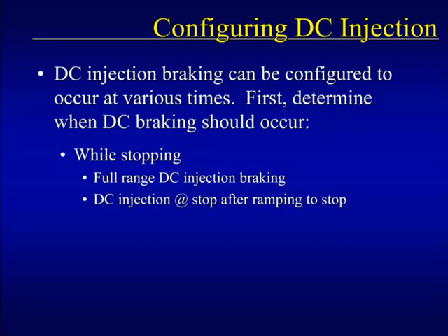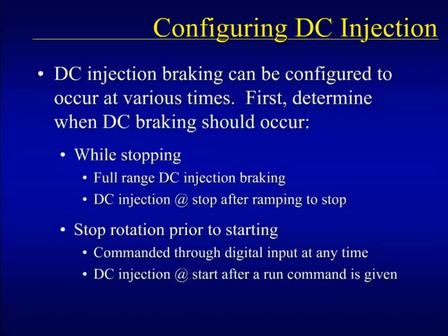The second condition is to provide braking to stop motor rotation prior to a run command being issued. This can occur either through a digital input commanding the drive to DC inject, or it can occur for a predetermined amount of time once a run command has been issued.